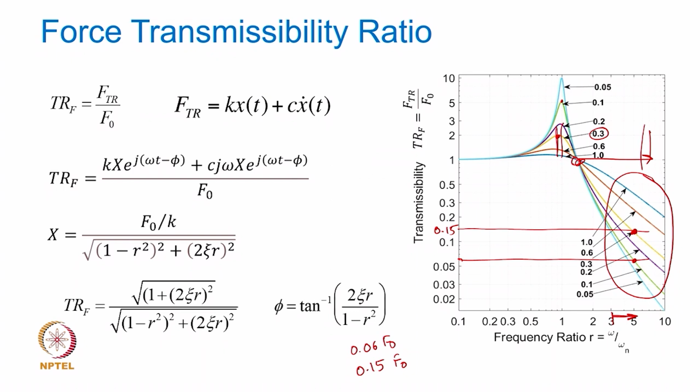And therefore, you should have a calibrated damping in the sense that damping should be just enough to ensure large amplitudes or large force is not transmitted during resonance, but you must have as low a damping as feasible so that the transmitted force is minimized in your normal operating range, which, if you design things properly, is going to lie in this particular zone. Okay.